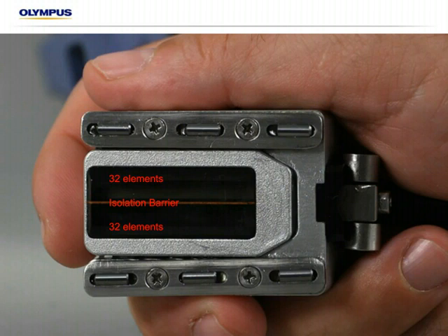You can see a few other things here. We have some carbide skates in order to preserve the probe, and the same adjustment system as the Rexolite, which allows us to put it on the pipe surface or other curved surface, push down and then lock it into place at the right height to adhere to different curvatures.